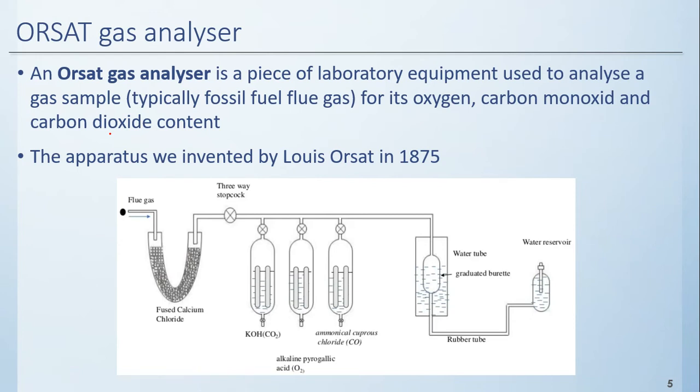So say you are running an automobile using a fossil fuel, say petrol or diesel. Now, when you measure the quality of your exhaust gas, then you can have a small analysis about your combustion, and you can come to a conclusion about your engine performance. Say your exhaust gas has a huge amount of carbon monoxide, then that indicates an incomplete combustion in your engine.